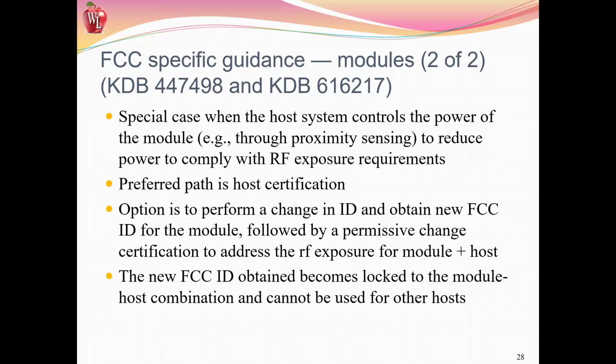They prefer to have a host certification. The option is to do a change of ID and then follow a permissive change certification. And the permissive change would then have to address the RF exposure for the module in that host. A new ID can be obtained, but the module host combination is locked in for that ID. It can't be used for other hosts.